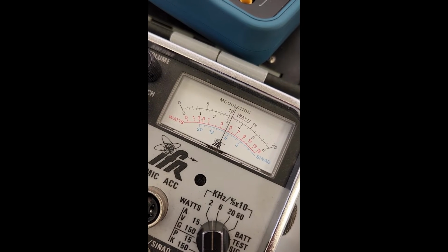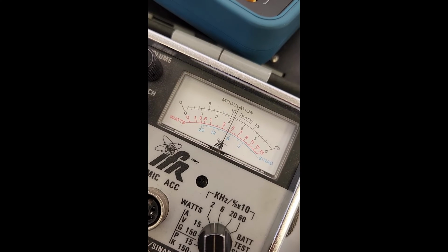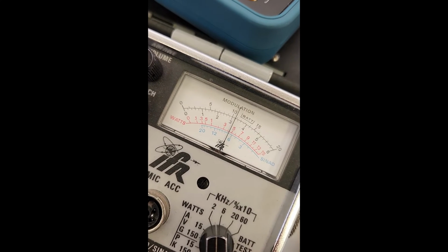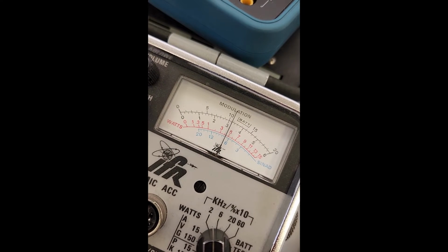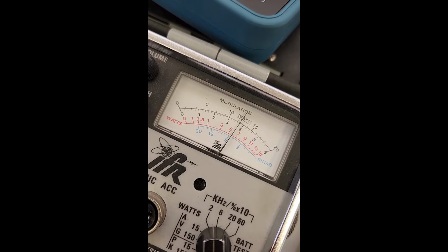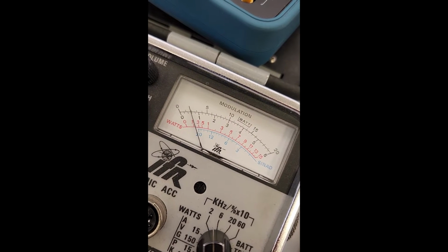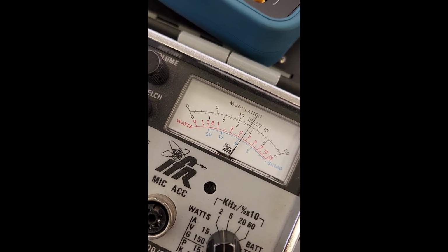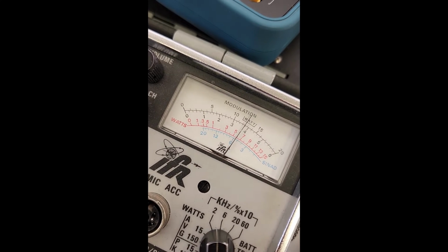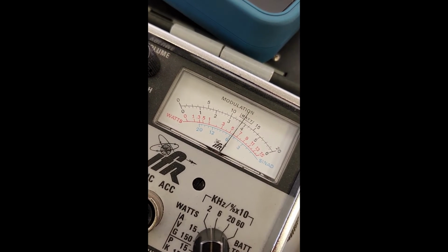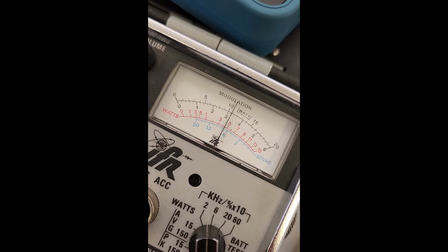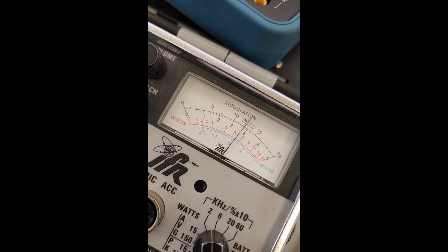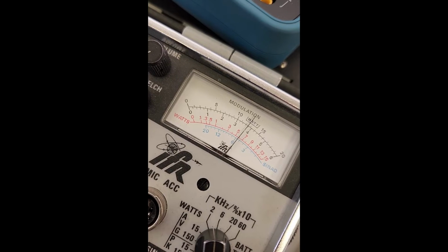If you're adding a PL tone, you want to make sure that you set your test tone to 3.2 kc deviation before you commence to encoding your PL tone, because it's going to add to it. I set my PL at 600 hertz, so we're going to have a total of 3,800 hertz of deviation if you add the PL tone. So always remember, you want to kill your PL tone before you set the level of your test tone, so you make sure that that's going to be okay.